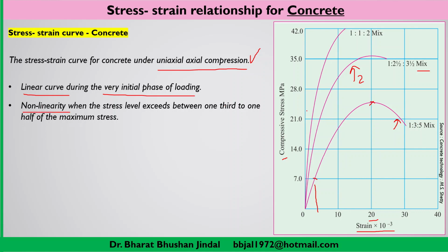From this diagram you will be able to see that non-linearity appears when the stress level exceeds between 1/3 to 1/2 of the maximum stress. Suppose the maximum stress is 35, then between 1/3 of 35 and 1/2 of 35, where 35 is the maximum strength of that particular grade of concrete, you will find that the curve is non-linear. So that means it is not an elastic relationship now.